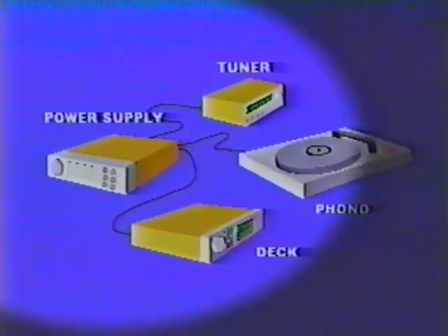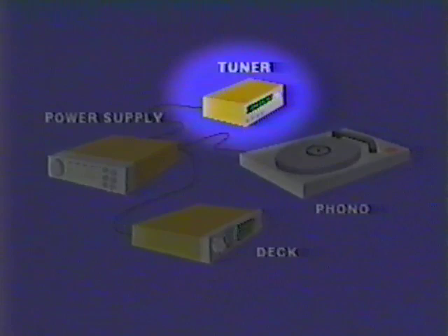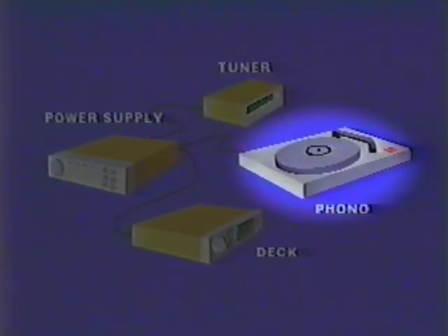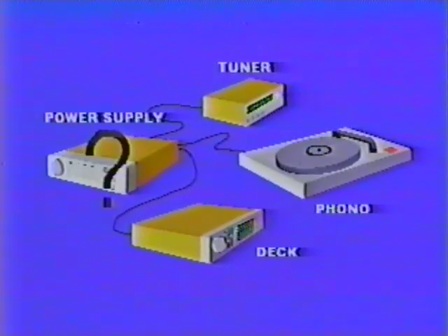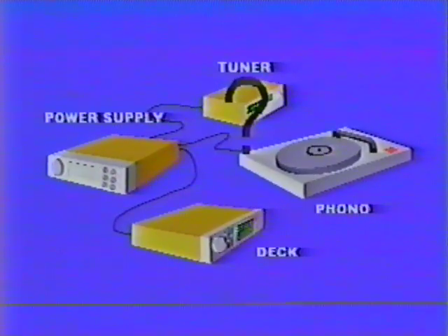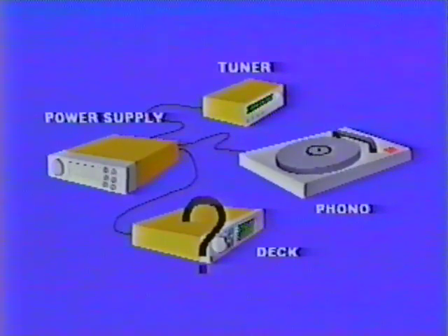When diagnosing a power supply problem, you should always remember that a power supply failure can be produced by either a component within the supply or by the signal processing circuit connected to the supply. When the problem in the supply has been corrected, the technician should carefully consider the source of the problem. Oftentimes, a supply must be repaired twice. The first repair fixes damage to the supply, but a second repair is needed because the technician didn't find the original cause of the problem.